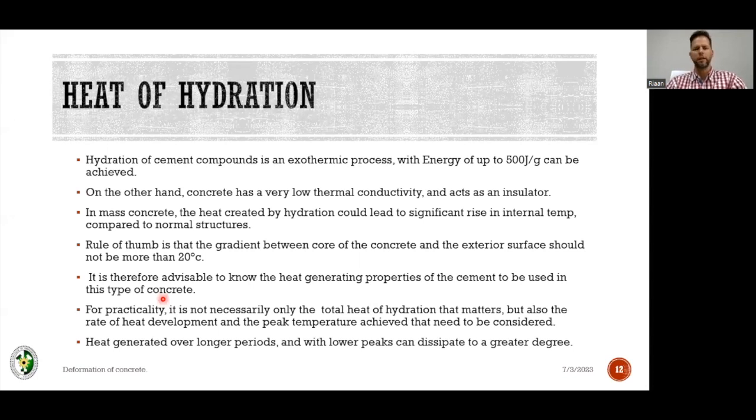So they further extended. The ultimate extension was 65% of fly ash into this concrete, replacing 65% of clinker. That's the ultimate extension that they settled on, and they took a bunch of cubes. So they were constructing this dam for a year or two. And the cubes taken, by the way, they were scalped cubes. Scalped cubes means that the aggregate particles in some of these, well, in this mix, I think the maximum aggregate particle was 65 millimeters. That's as large as your fist.